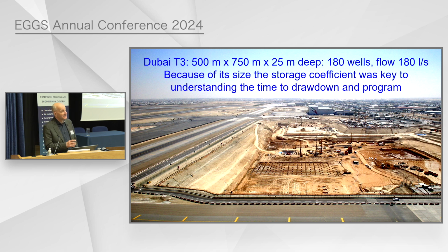There's always an exception. This is an exception. Big excavation in Dubai in sand. Actually, we could dewater it quicker than they dug it. It was all to do with the way in which the site was released, which caused a problem with timing, and the excavation program was in fact controlled by the storage coefficient. So there's always exceptions to almost everything I'm going to be saying.